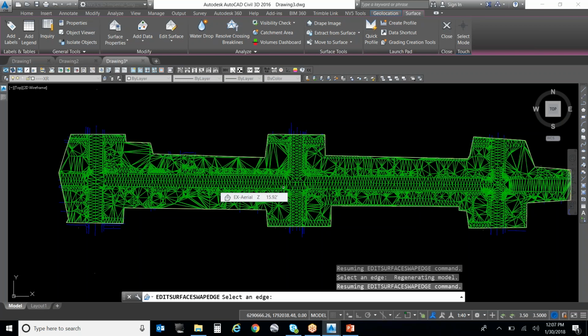Well, what if there's 100 points here and 100 there? Then you create two different surfaces. Or you create one surface and draw a boundary. Right, okay, and so again, let's say I have a good density of data from this line to this line. What I'll do is I'll subtract out of this surface and cut out the aerial data, and then I'll cut in the survey data, okay? At some point, you paste it in, but the margin that you use depends on how close your data is, okay?